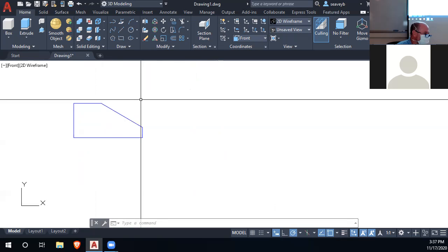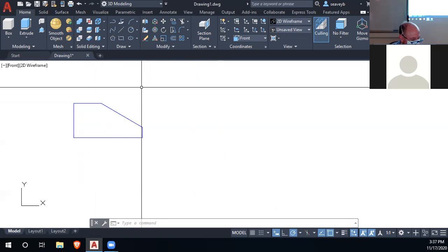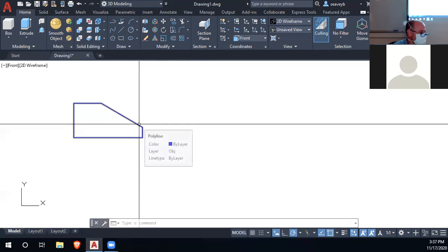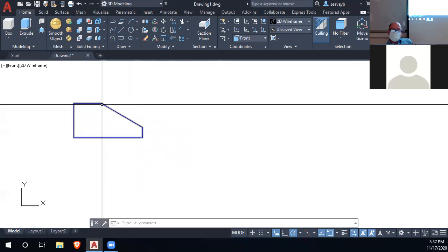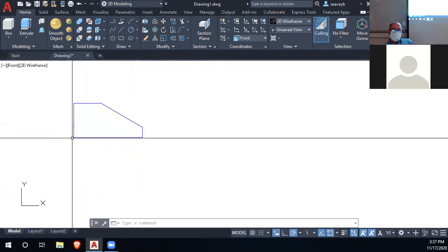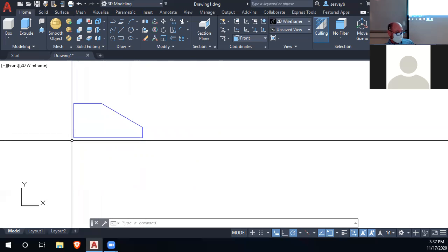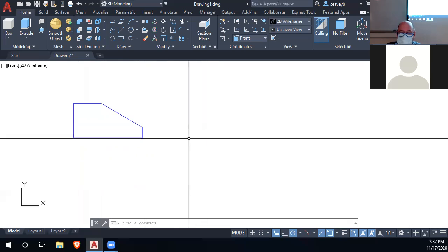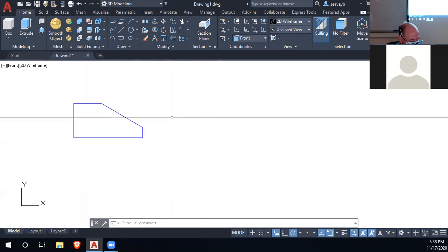So that top line on top is what size? Yeah. 2? Do you see why it's 2 in the drawing? So you go 2 up and then 2.5. Starting at this corner where my cursor is, you go 2 left. 2 left. 2.5 down. You see why? And then 5 to the right. Then 3/4 up. So I'm using the other views, right, to get those numbers.